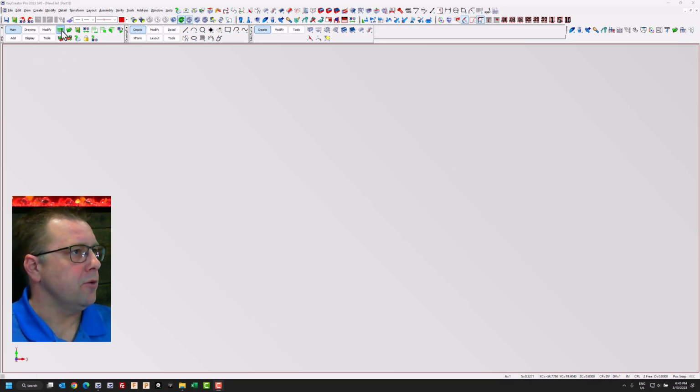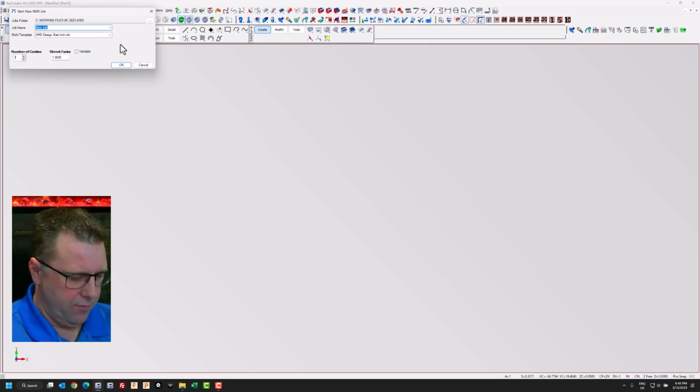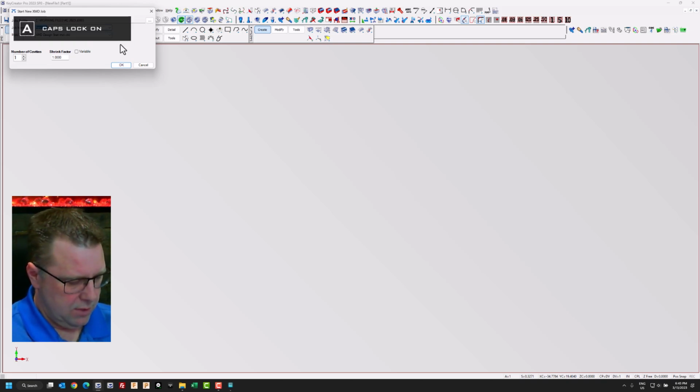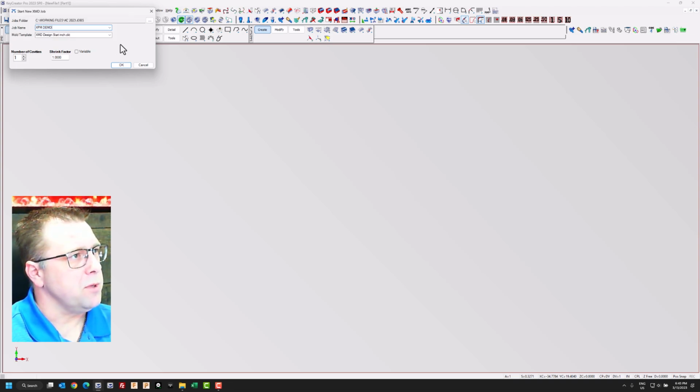So you're going to come up here and you're going to use our XPM, Expert Part Manager. You're going to give your project a name. So we'll call this XPM Demo. You can start with our standard design template, or of course any company or any individual can set up their own. How many cavities is this project? For our example today, it's only going to be 2, but of course you can do multi-cavity, you can do multi-material, multi-station molds, all different kinds of things. We're going to use 11.5 shrink, and that's going to automatically expand the part data for our project.